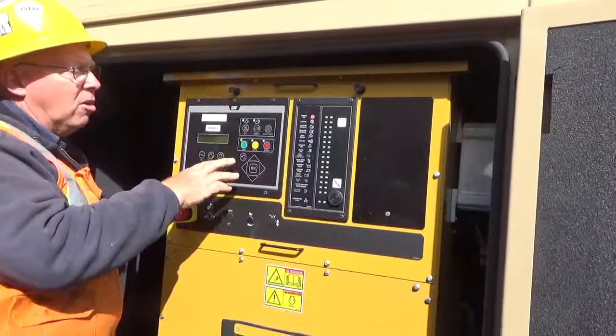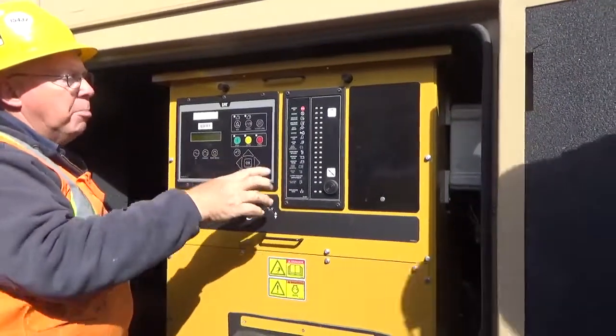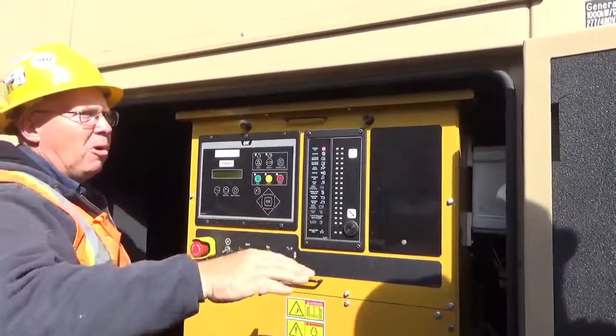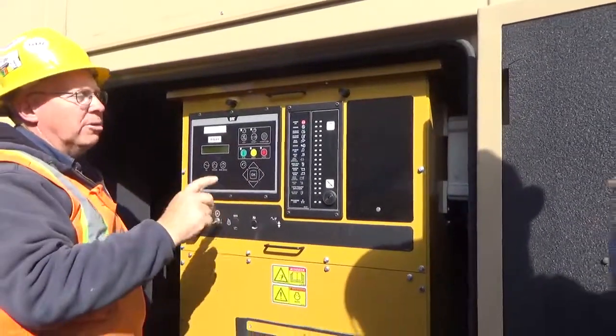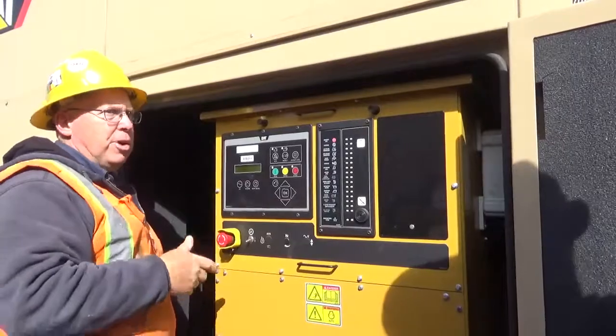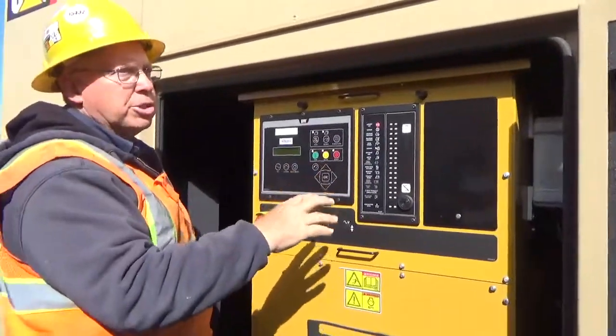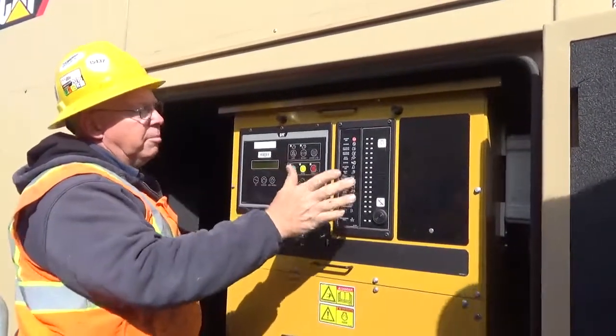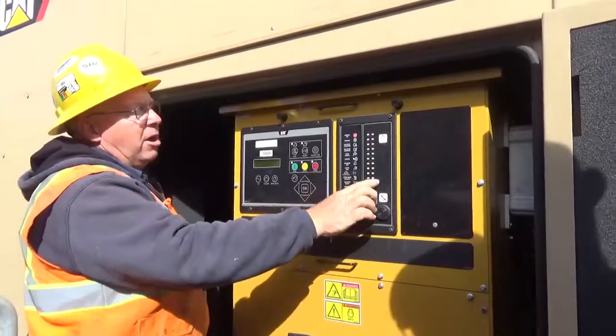So I cleared all the alarms out, and I'll show you how to read them. But anytime it's flashing, if you don't acknowledge it, make it go solid, it won't clear on its own. You got to make it go solid, then it'll clear on its own. So it can be in there for a week, if you don't make it go solid, it'll flash forever. So anyway, to look at problems, now we have a not in auto light on.